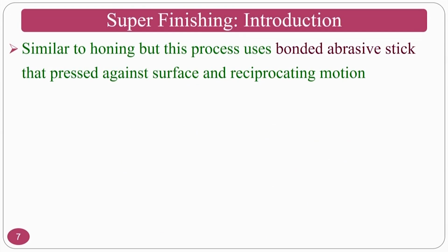Super finishing is similar to the honing process, but it uses a bonded abrasive stick basically, that is pressed against the surface, and reciprocating motion is provided to it.